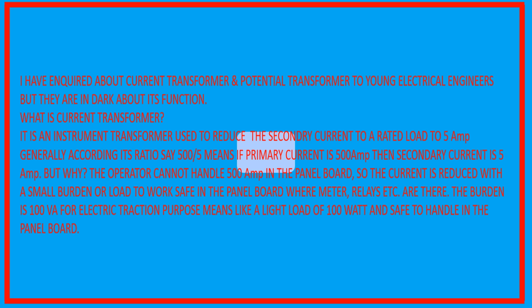But why? The operator cannot handle 500 ampere in the panel board, so the current is reduced with a small burden or load to work safely in the panel board where meters, relays, etc. are there. The burden is 100 volt ampere for electric traction purposes, meaning like a light load of 100 watt and safe to handle in the panel board.